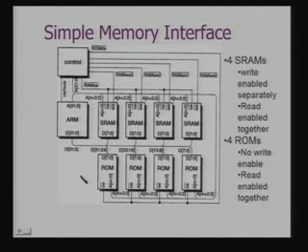Now, what we have seen here is that these SRAMs are write enabled separately. So, that means typically here I have individual write enable signals. The individual write enable signals are not coming from the ARM core; they are to be generated by the interfacing logic which is here. Okay.